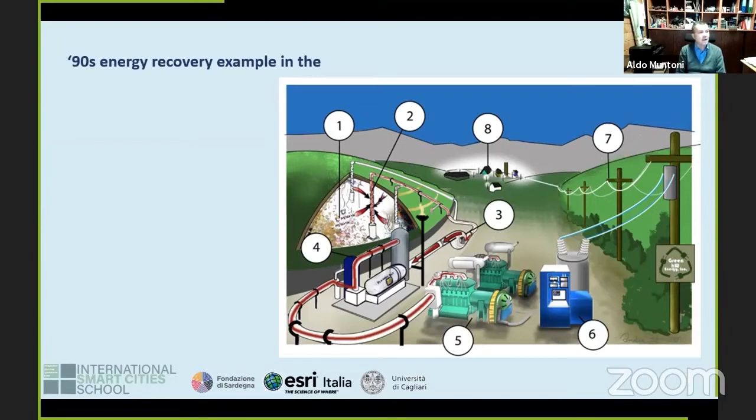And I remember that I helped him to design a lot of systems for the collection of biogas from the landfills, for delivering the biogas to gas engines, and these gas engines produced electricity to be used in the nearest town. And also, since we need to cool down the engines, the heat was recovered to produce steam.